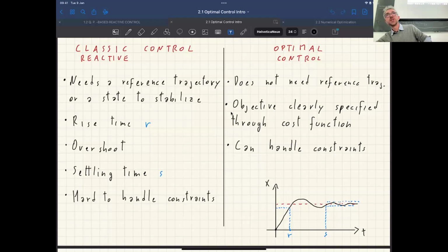So yeah, more recently, actually, there are people who have been achieving this kind of very complex motion generation in real time, where the solver is taking care of figuring out which contacts to make and to break, and generating the whole motion of the robot, and doing that in a model predictive control fashion. So it's a real-time optimal control.